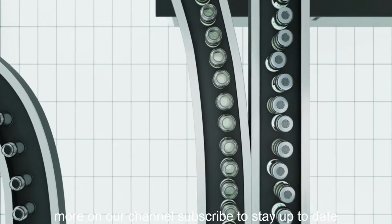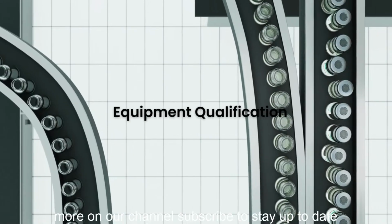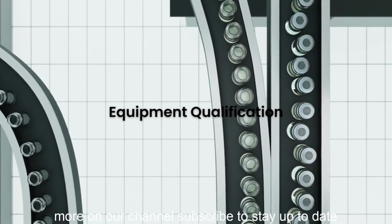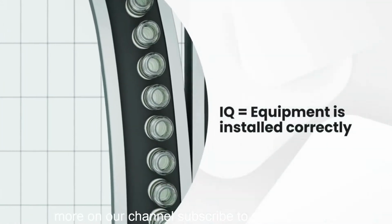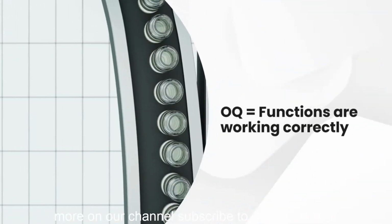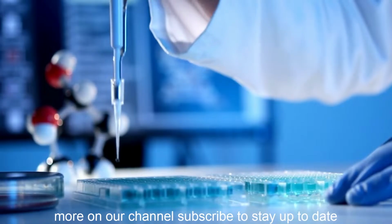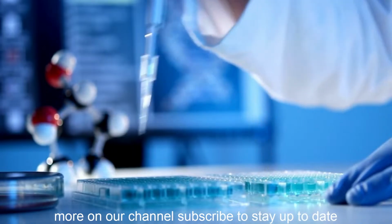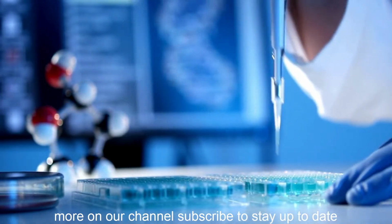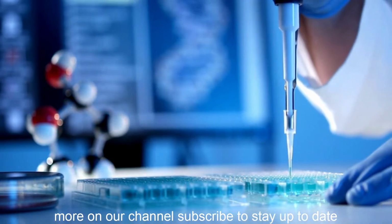This applies to all critical processes, from mixing and compression to sterilization and packaging. Equipment qualification is also part of this rule, ensuring that equipment is installed correctly, Installation Qualification, IQ, operates according to specifications, Operational Qualification, OQ, and performs reliably under actual production conditions, Performance Qualification, PQ. Analytical methods used for testing raw materials, in-process samples, and finished products must also be validated to ensure they are accurate, precise, specific, and suitable for their intended purpose.